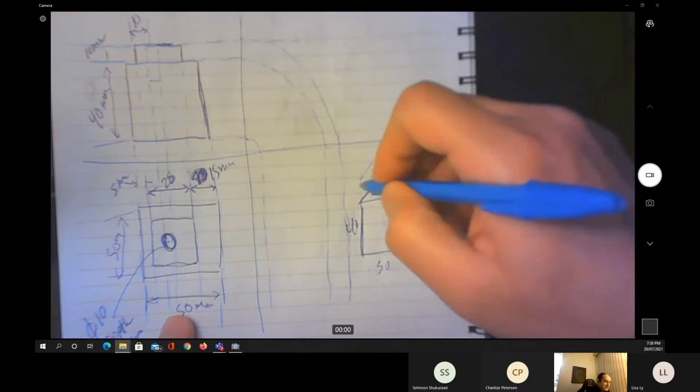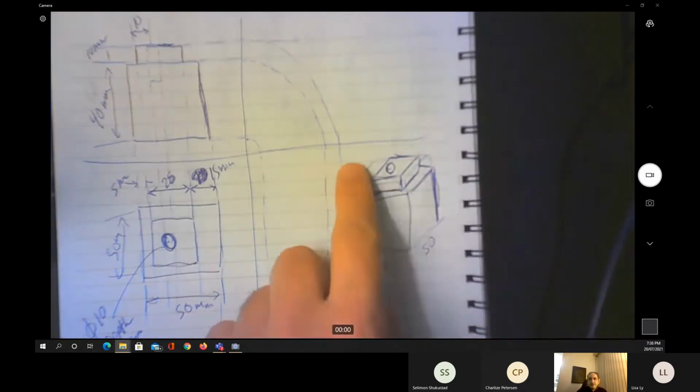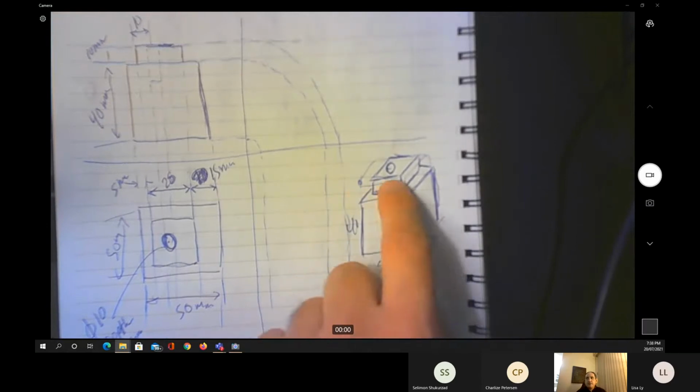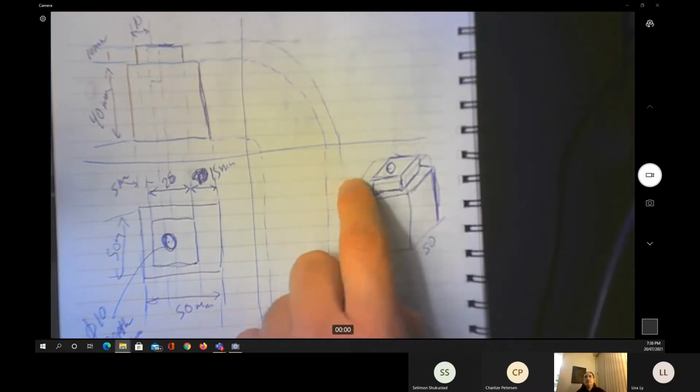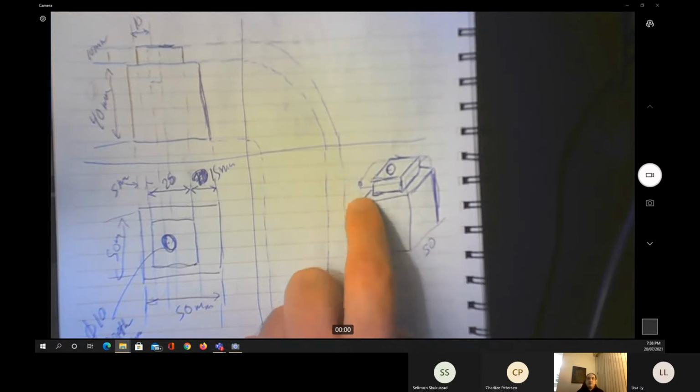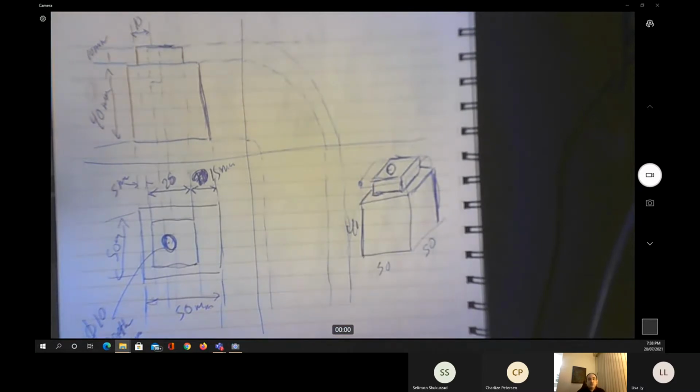Okay, this will be my origin point, and everything is going to be a reference to here. Less than that is going to be minus 10 millimeters. Definitely, if I try to remove the material to the depth of 10 millimeters, you need to do it at least in three steps. The first step is going to be 4, the second step is going to be 4, the third step is going to be 2.